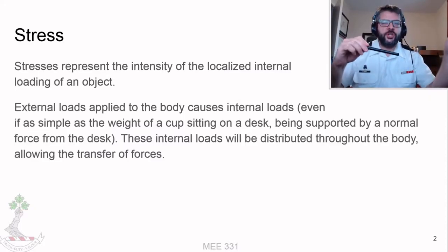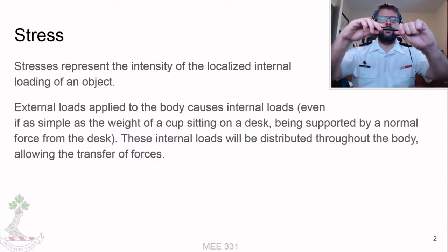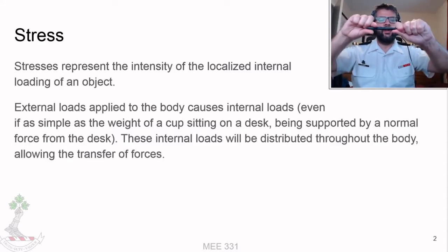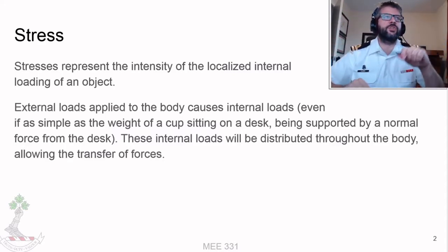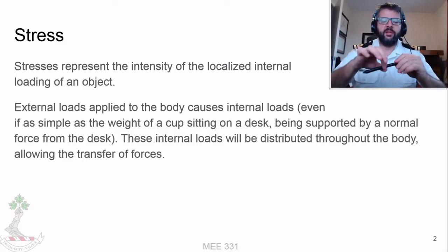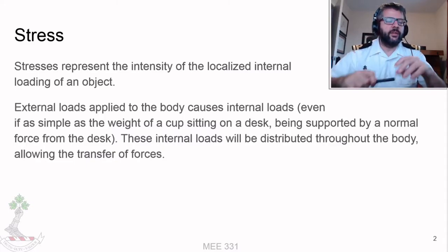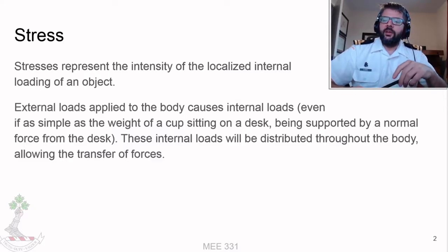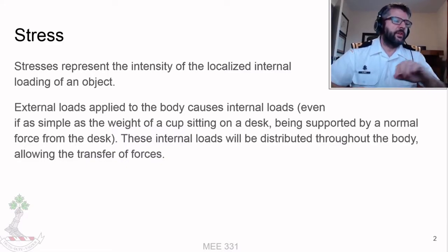If we're talking shear, say I'm holding this pen here and pushing down on this one side, then I'm applying a shear load, and that's also going to be shared over that area. Now, unlike the tensile stress, it's not going to be shared as evenly, but even the tensile stress can't really be said to be shared completely evenly because there's going to be some uneven distribution of the load.